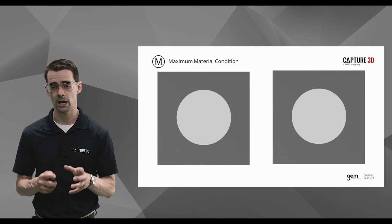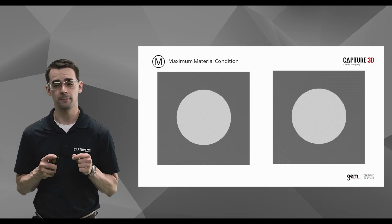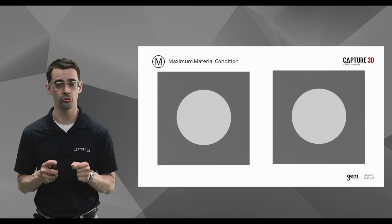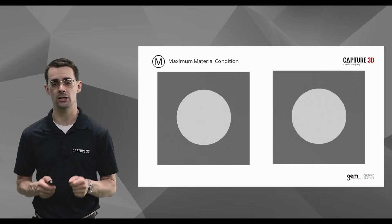This is the idea behind maximum material condition. We specify the position required at a hole's smallest size or a pin's largest size, and we get a bonus tolerance based on the size deviation from this.